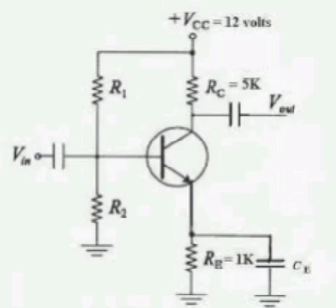Reactive power dominance: high reactive power. At low power factors, the system has high reactive power, which does not contribute to real work but still influences the total current. Measuring instruments may misinterpret the reactive component, thereby affecting the real power calculation. Apparent power calculation: since apparent power includes both real and reactive power, a higher proportion of reactive power leads to a larger discrepancy between real and apparent power. Accurate measurement of real power becomes more challenging as the real power component is relatively small. Accuracy of instrumentation, instrument error characteristics, calibration, linearization, measurement of small real power, proportional error increase.